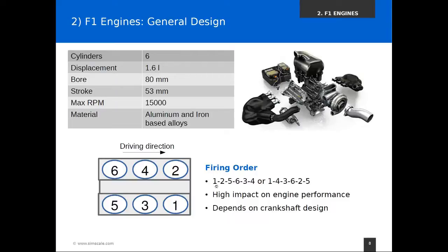So when we fire those cylinders, they do not all fire at the same time, but one at a time, and there's a certain order. I will not talk too much about this order, but the purpose behind this is to keep the engine vibrations low and to have a smooth delivery of torque or of engine power over the entire revolution of the crankshaft.